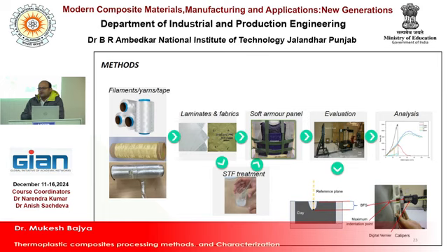This is the clay. I would like to say it represents the human body. So in the back side you can see this is clay-like material, toy clay. Then you put the jacket on this clay, and you need to fire as per the threat level. It is not the case that every jacket is provided for every kind of threat. Like for pistol the requirement is different, for AK-47 the requirement is different, for sniper the requirement is different. So according to that you need to design the jacket, you need to prepare the composite panel.